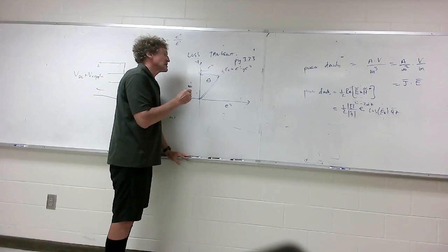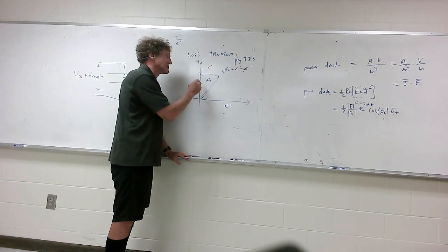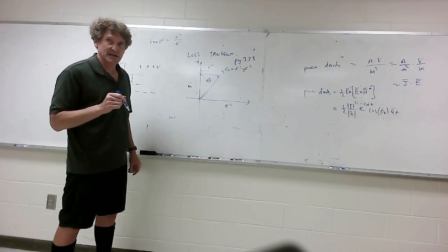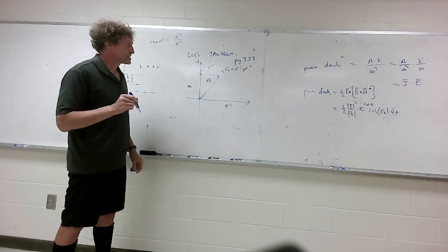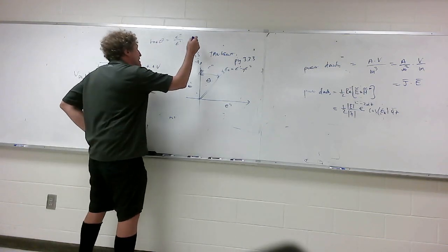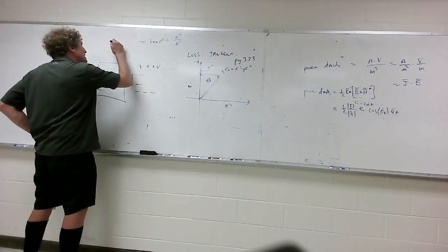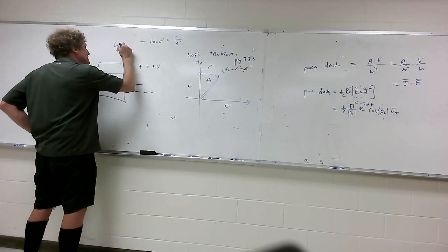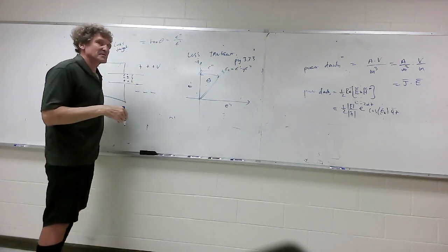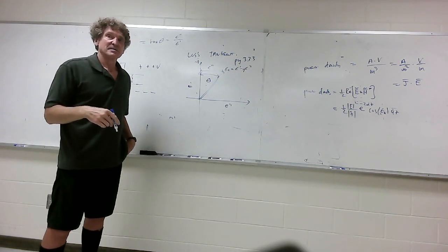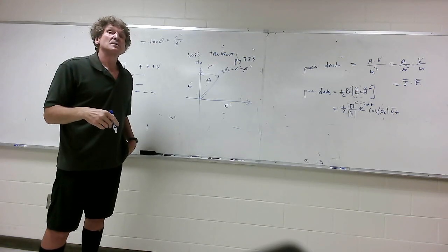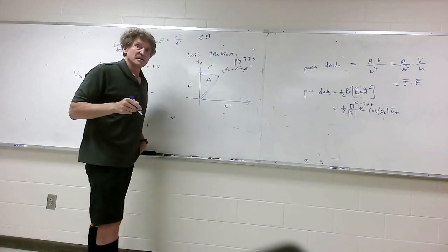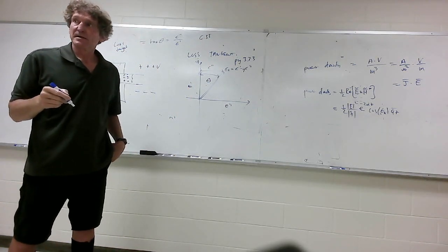The loss tangent is really this angle. And what it is, is the ratio of epsilon double prime over epsilon prime. He has that if you look, right? Yeah. What equation is that? This is called loss tangent, equals sigma over omega epsilon. Take a look at equation 6.55. Is that the one? Yeah, that's the same one.